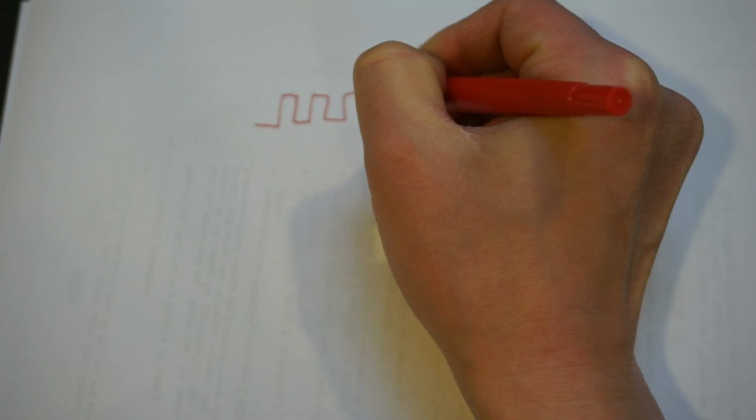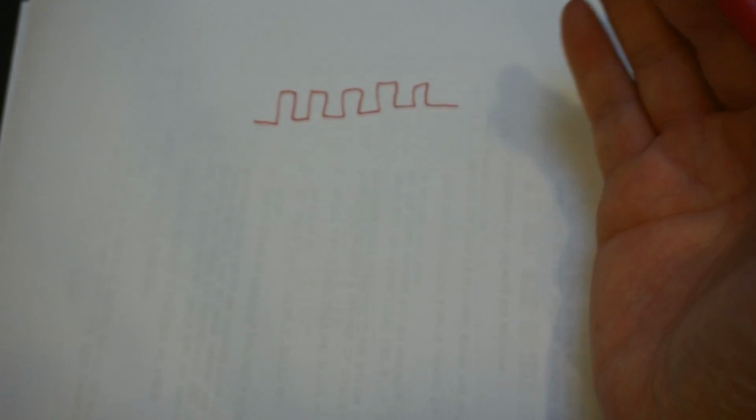So let's take a look at how a frequency counter works. In general, there are a couple of ways for counting frequency. The first one is probably the most popular one, and it's very intuitive. We have a signal here, so let's just draw it here. This is my incoming signal. And basically the idea is if I open the gate for a predefined number of seconds or predefined period,